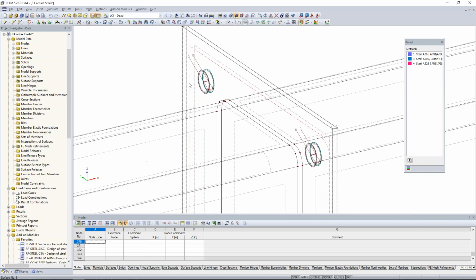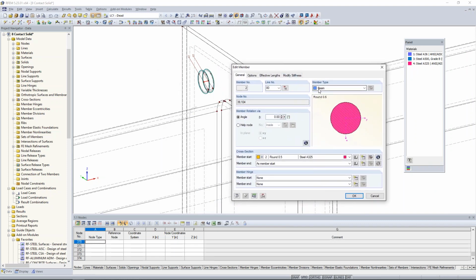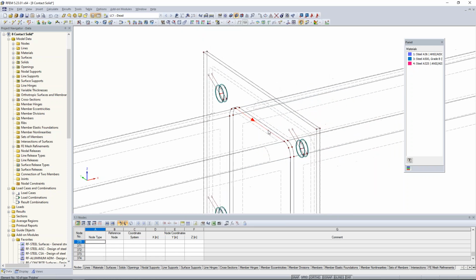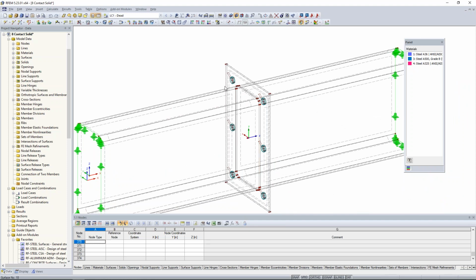Now, the other final thing to note is that, of course, these plates are going to fail in tension, so we need something to hold them together. Well, I have modeled some just typical member elements here as beams, and these are just circular steel sections with a 1-inch diameter to represent my bolts. So these bolts should take over on tension when the plate elements fail.